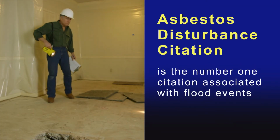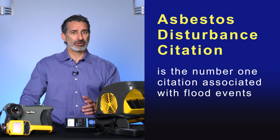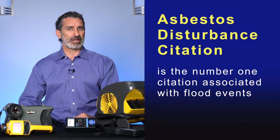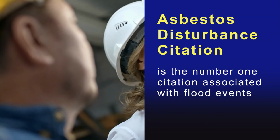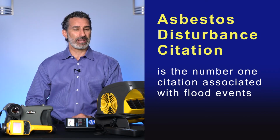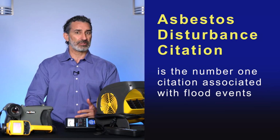As an example, the number one citation we see associated with flood events is the inadvertent disturbance of asbestos. The restoration company comes in, attempting to be helpful, and very quickly starts cutting out building materials to speed your drying process, but does not check to make sure the regulated material, like asbestos, has been tested. And a regulator will come to the site and they cite everyone that has command and control of the building. Obviously, they would cite the restoration company, but they would also cite building management. They would cite the building owner.